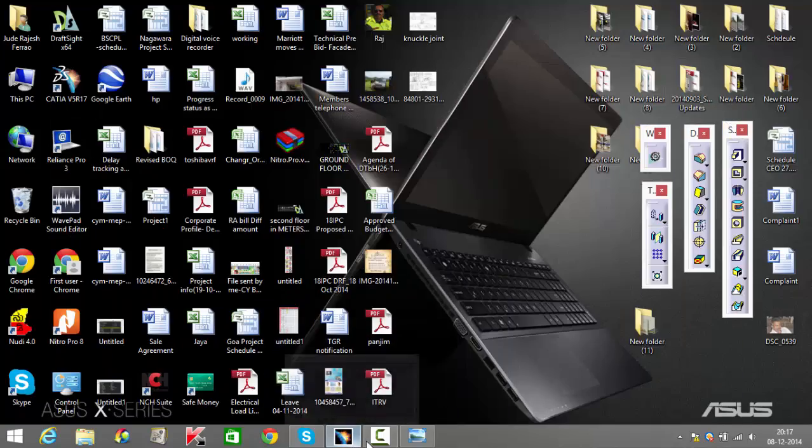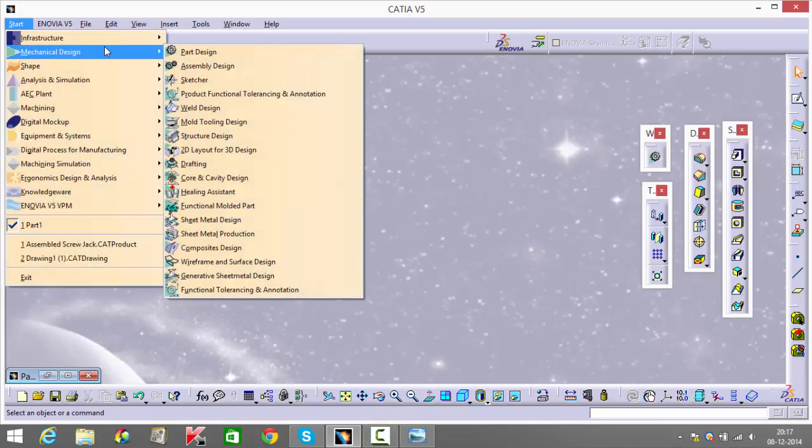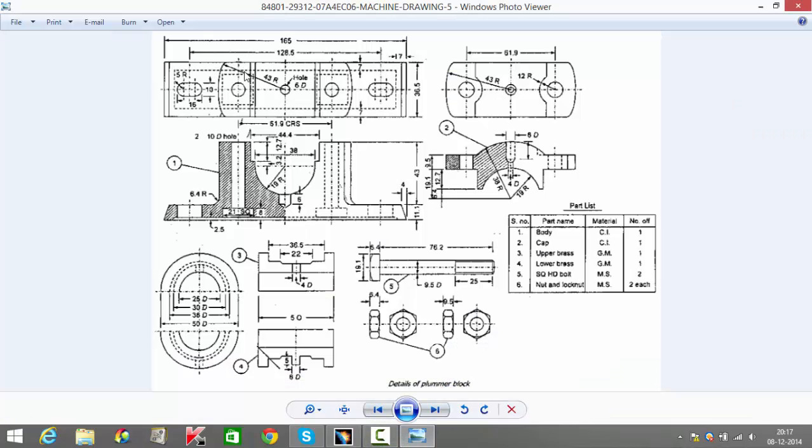And this took us what, 15 minutes to do. You're now going to just make another part design, and we're going to make part 2. Part 2 is this portion. I'm again going to treat this as my front view and this is my top view. I'm basically going to draw this entire portion and give a pad, and then you'll figure out what I'm doing. When I'm drawing my figure, I'm going to draw it only up to this point and this, and just as how we got the sort of curve over here, we're going to do the same over there.